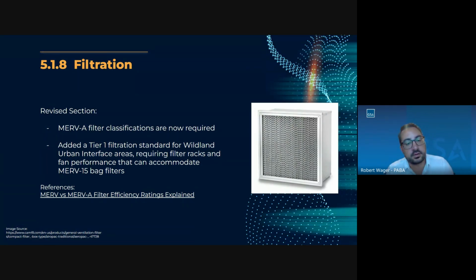Another update is under the tier 1 performance standard: we added a standard for wildland urban interface areas requiring filter racks and fan performance that can accommodate MERV 15 bag filters for any sort of wildfire smoke and whatnot. And there are some references here that we'll share with you following this training.